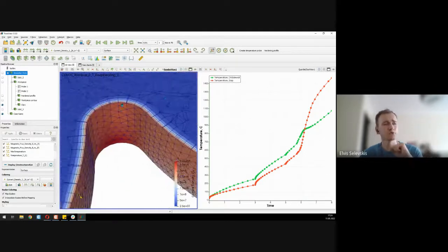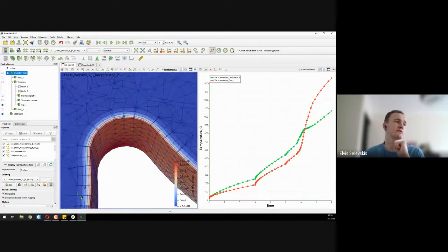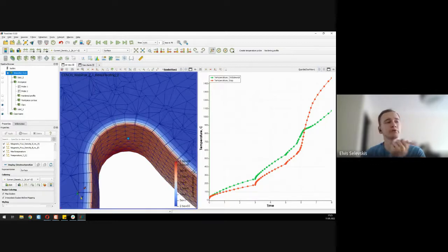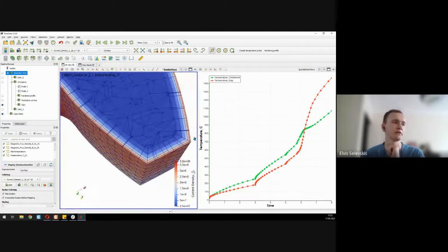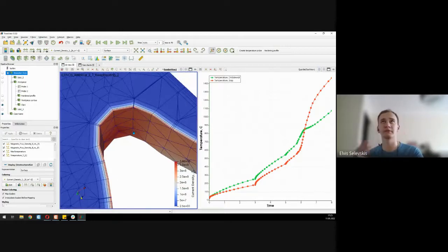So a couple of tips here from my side. Basically, with the viscous layers, what you should be able to see is that the first element is a lot redder than all of the other ones, and that the current density slowly starts to soak up into the workpiece. And the perfect variant is that you're using all of the viscous layers very evenly, very nicely, so that the pattern changes nicely and slowly.